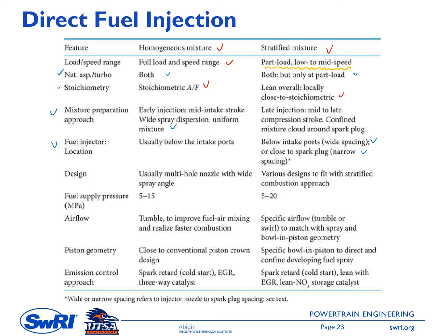For the injector design, usually we have a multi-hole nozzle with a wide spray angle for homogeneous mixture. Once again, we need a good injection system for homogeneous mixture. One way to have that is by having a multi-hole nozzle injector, so the hole size is smaller and the hole number is more.